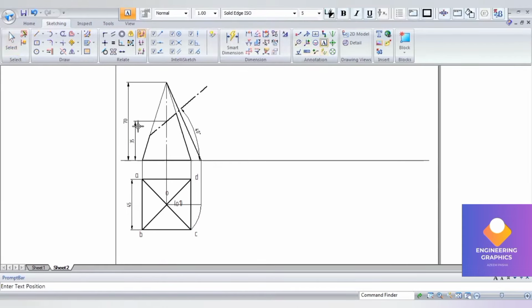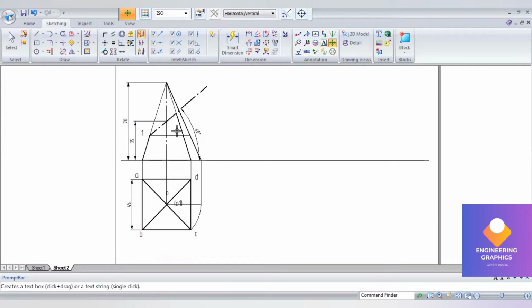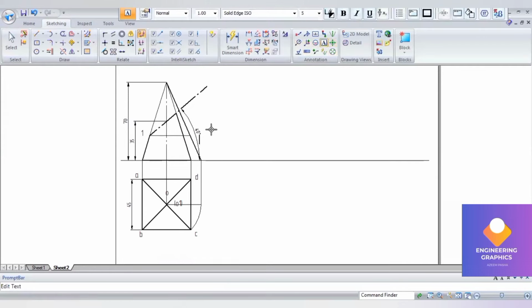Now we can mention the cut points here. Cut points 1 and 2 occur on the same point, and 3 and 4 occur on the same point, but we have to draw horizontal lines here to indicate. I'll be drawing the horizontal lines to that newly formed slant edge length, so 1 and 2 exist on the same point. You can mention that 1 and 2 are on the same point.